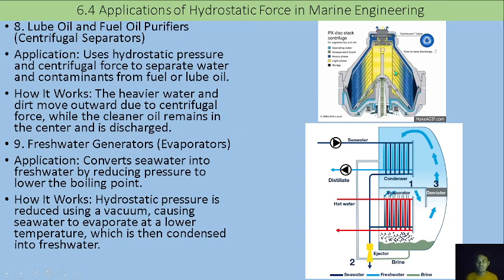Okay, another application of hydrostatic force in marine engineering is for lube oil and fuel oil purifiers. This is the purifier, as you can see. It uses hydrostatic pressure and centrifugal force to separate water and contaminants from fuel or lube oil. The heavier water and dirt move outward due to centrifugal force, while the cleaner oil remains in the center and is discharged at the clean oil outlet.